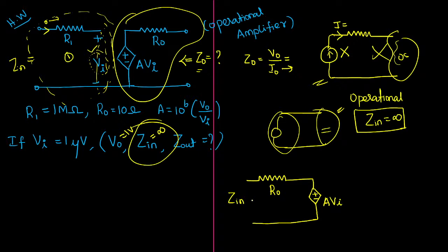In order to know the value of output impedance when your circuit has a dependent source or independent source, let me apply Thevenin's theorem, because I may not be able to calculate the output impedance directly. When a circuit has a dependent source, what is the procedure to calculate the Thevenin impedance? See, it is the output impedance, sorry. What do we have to do? First step, identify the load terminal. This is the load terminal where we are going to calculate the impedance. Remove the load from the load terminal. Yes, it is removed. Then, when your circuit has dependent sources, deactivate all independent sources.